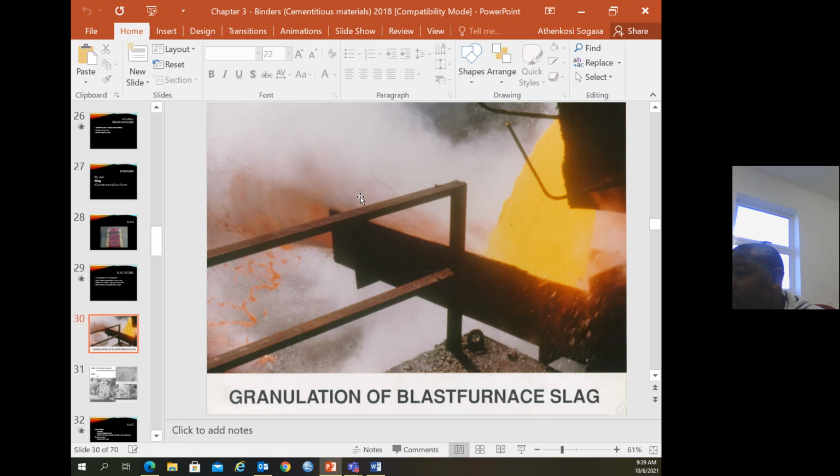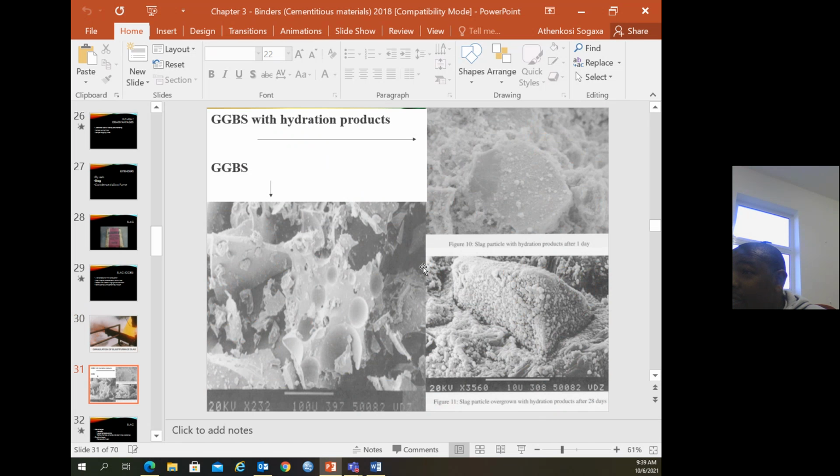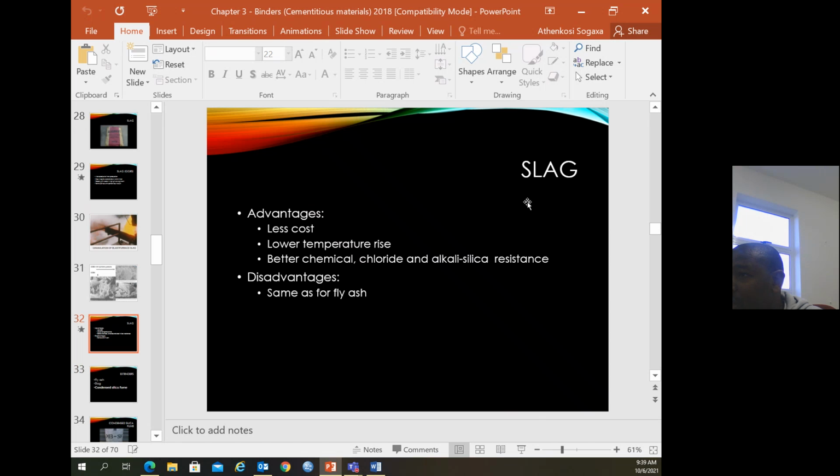Now you can see where that comes from. So now GGBS with hydration product, therefore you can see that. You can see the pictures of it. That's not important. The advantages of the slag: it's less cost, lower temperature rise, better chemical, chloride and alkali resistance,